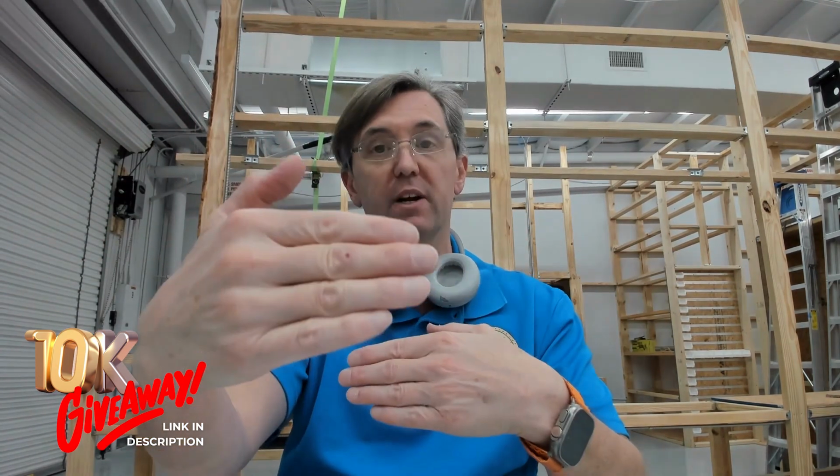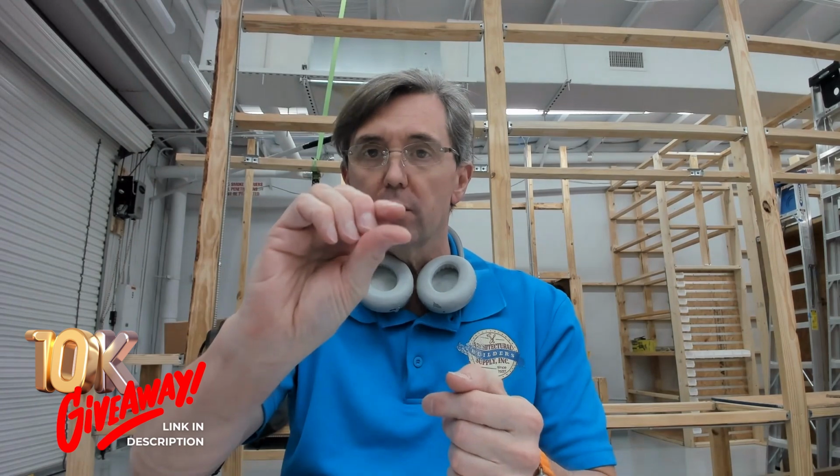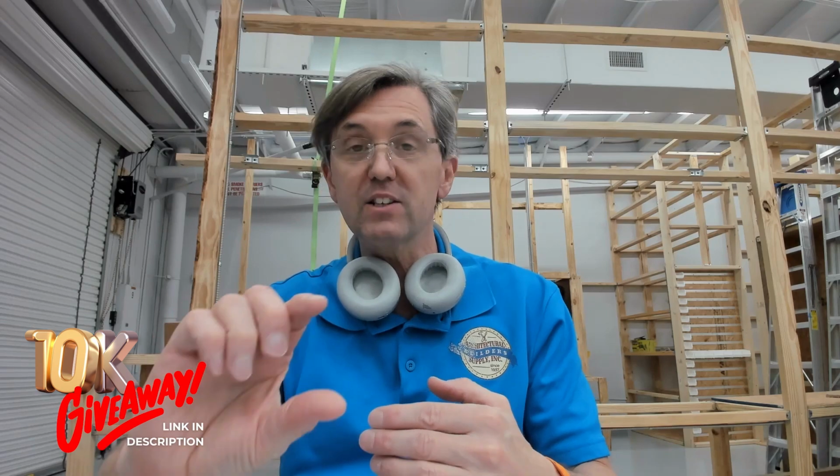The second toolpath is now 21 by 21, 3/16 deeper, come up with a step. So I'm cutting that toolpath, but now I'm air cutting the first 3/16. And to add insult to injury, the next one is 20 by 20, and that's 3/8 deep. So now I'm air cutting 3/16, air cutting 3, because that's my pass depth, before I get down to it. And I realized, well, this just doesn't seem right.